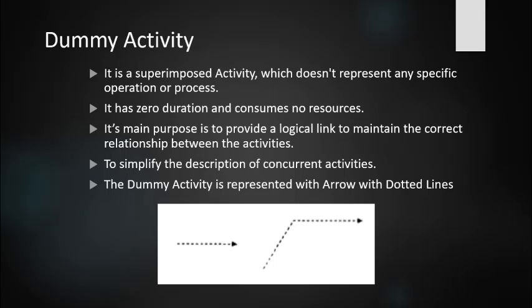So in between the activities, the earthwork and the bar bending, there is an interlinking, a relationship between these two activities. So you have to monitor these two activities simultaneously with a dummy activity. In the chart, you have to represent the arrow mark between the two activities with dotted symbols. I will show you one diagram over there, so you will get the idea about this.